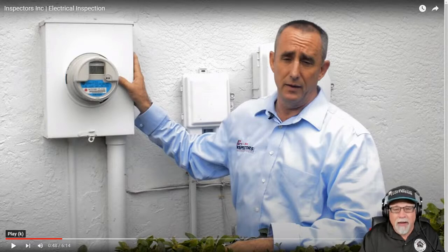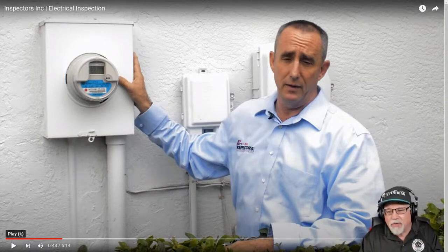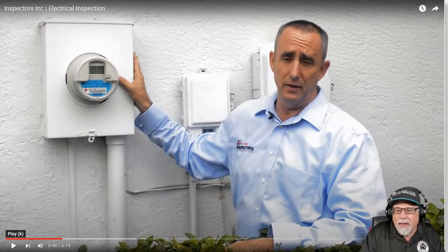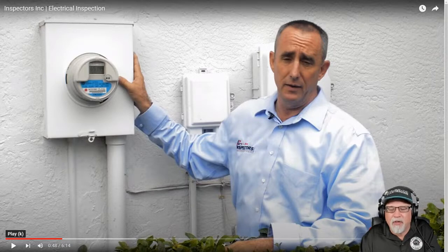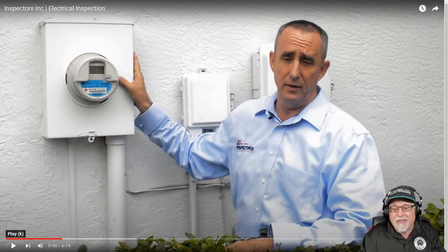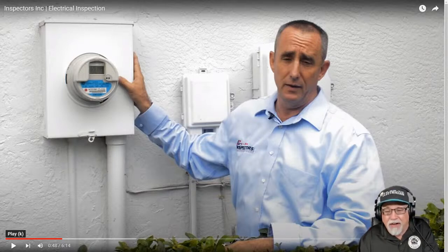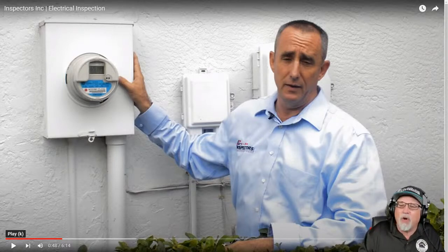But if you have a water pipe ground, the way he states it, it can be this or that. That's not true. If you have a water pipe ground and it qualifies, it has to be supplemented with another type of electrode. And it can't be supplemented with another water pipe. It could be supplemented with additional ground rods, but it's not an or. So that's the first thing.